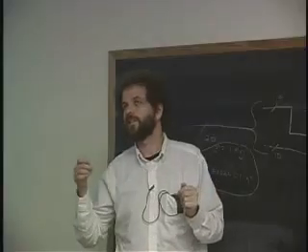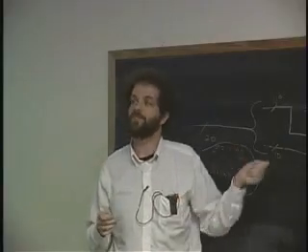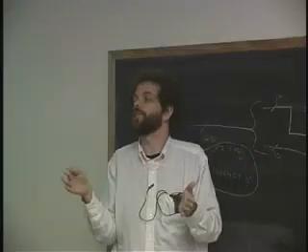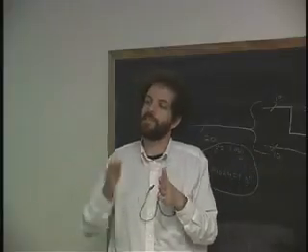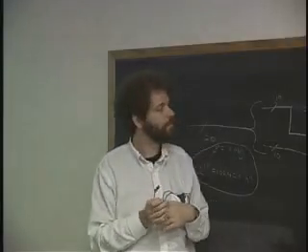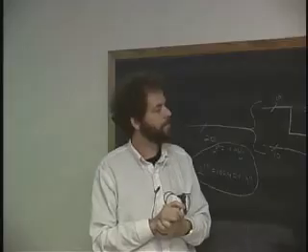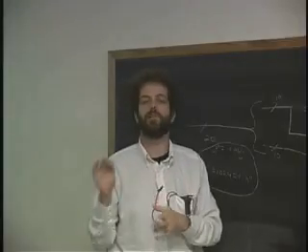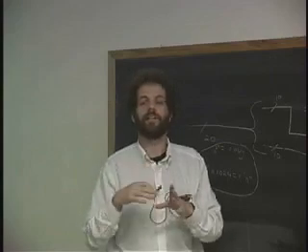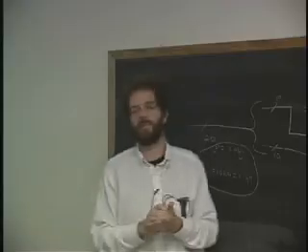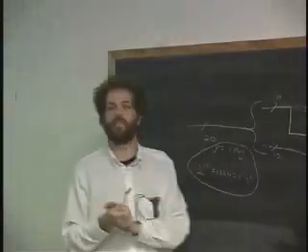Now, we're going to learn in the last third of the course that we're not actually going to do that. In other words, the computer will be set up so we could fill it up with that much RAM, but we're actually going to fill it up with less. In this case, we'd have a series of chips that would each pull out a couple bits to get our 32-bit total. We could do that, or we could actually leave big holes, and I'll show you a way of faking the fact that we don't actually have all the RAM that we thought we had. Okay, but that's towards the end of the course, so let's not do that now.